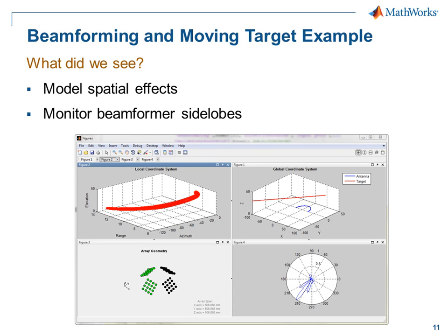We could also have added a jammer and monitored the SNR at the output of the beamformer. Finally, we assumed a narrowband antenna, but we could have used a wideband antenna along with a time delay or subband beamformer instead.